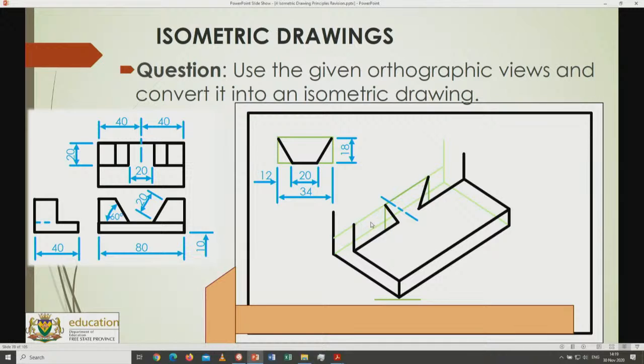And then from there on you can complete the rest of the drawing by simply joining the lines and going 30 degrees outwards, and measuring the distances of 20 millimeters. And then from there on, remember the depth is 20 millimeters, so all those lines going deeper in are 20 millimeters, and there we go with the complete part of this block over here. Most important, for non-isometric lines, you have to keep the auxiliary view and you have to keep the frames that you've been using in determining those points over there. Without those, of course, you will lose your marks. The examiner is asking for those points and wants to see where those points come from, and then of course you will not get your marks if it's rubbed out afterwards.